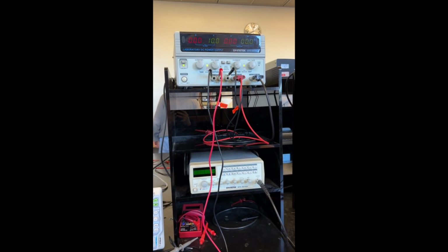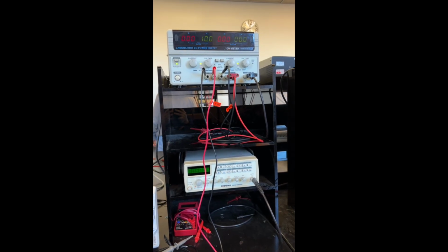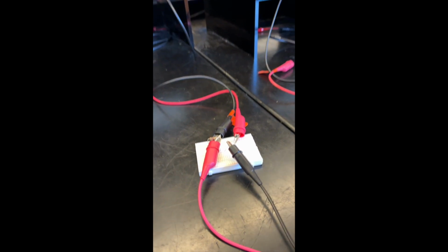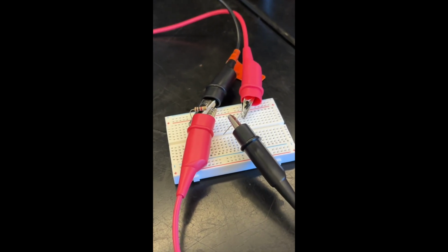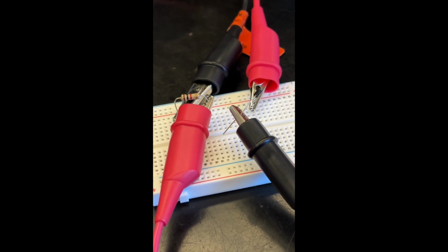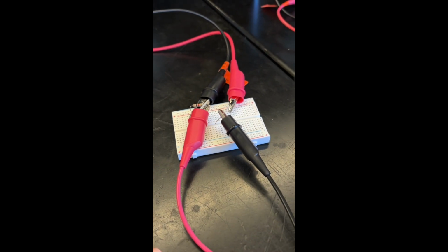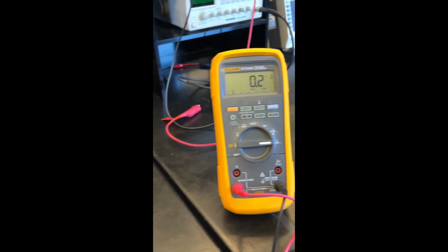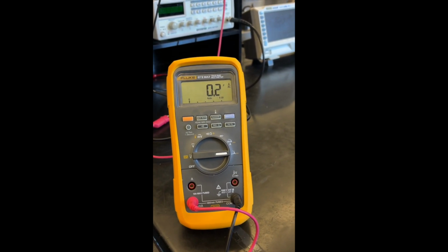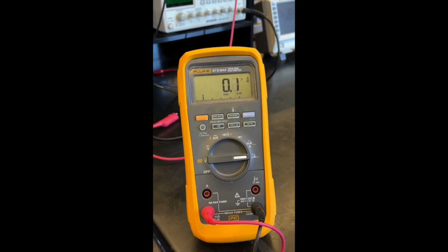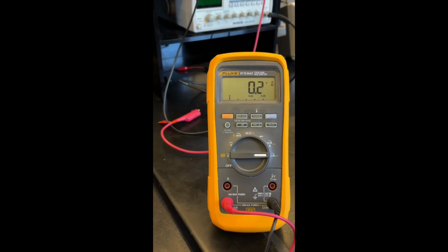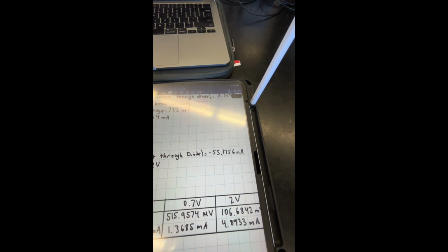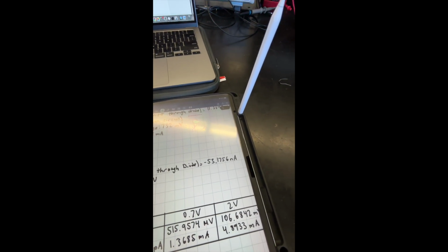All right, now I'll be looking at the leak current from my diode. So I'm still supplying negative 10 volts. And to measure the current across the diode, I've broken my circuit and connected my multimeter clips in series. And I'm getting a reading of 0.2 microamps, or about 0.1. And I simulated negative 53 nanoamps, so they're both very small